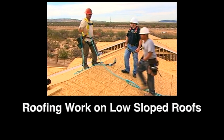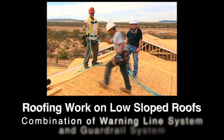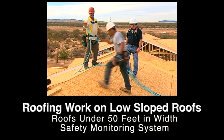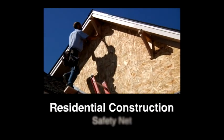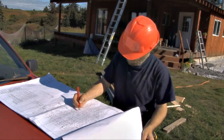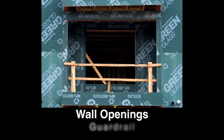Roofing work on low-slope roofs: guardrail, safety net, PFAS, or a combination of warning line system and guardrail system, safety net system, PFAS, or safety monitoring system. Roofs less than 50 feet in width may use a safety monitoring system alone. Residential construction: guardrail, safety net, or PFAS. When it is unfeasible or creates a greater hazard to use these systems, an employer may develop and implement a fall protection plan. Wall openings: guardrail, safety net, or PFAS.